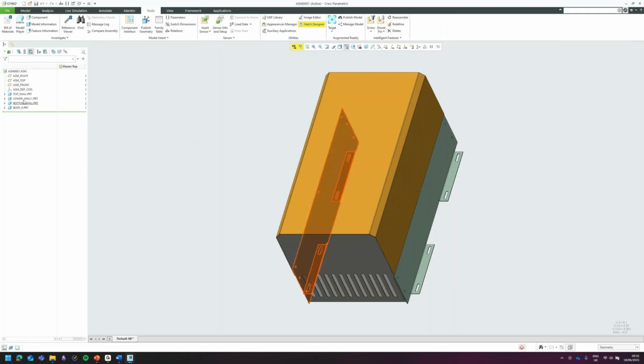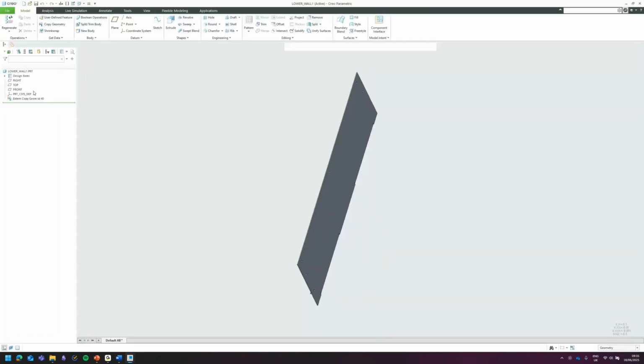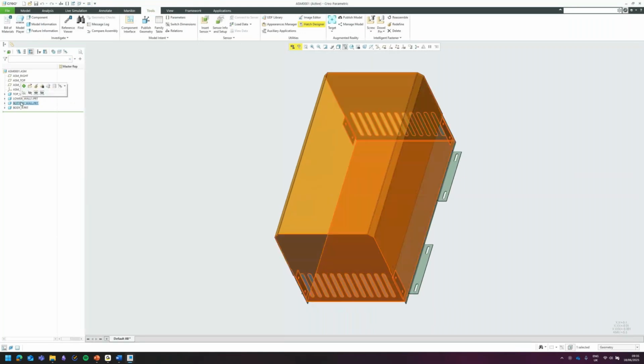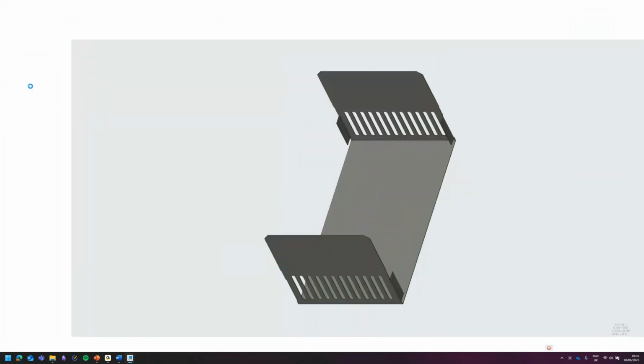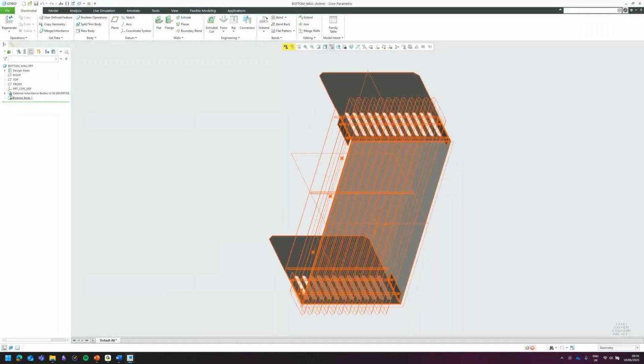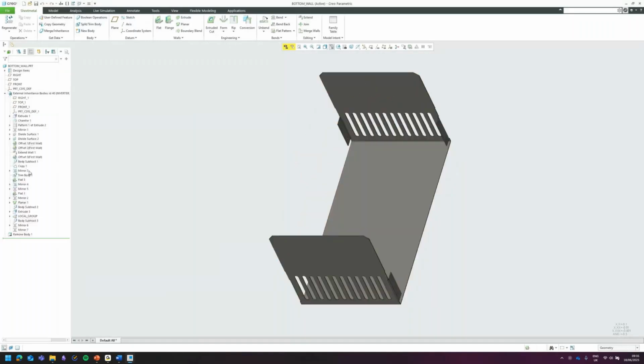But if we open, I can't remember which one I chose to copy geometry from, but just to show you the differences: by default, any solid geometry is going to be created with a copy geometry, but for sheet metal, we get the option. Here I chose to do a copy geometry feature. If we open up one of the other objects, where we have inherited features, we can now pull through the model tree from our original part. So we could make further alterations to this without affecting the original design part if we wanted to.